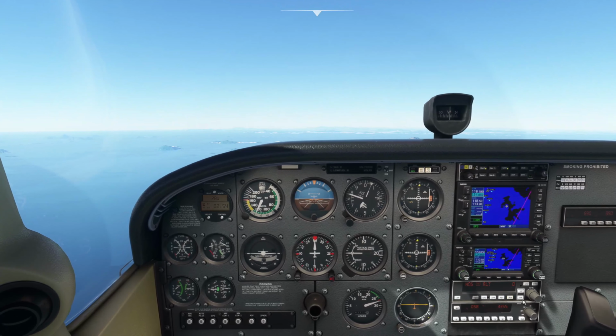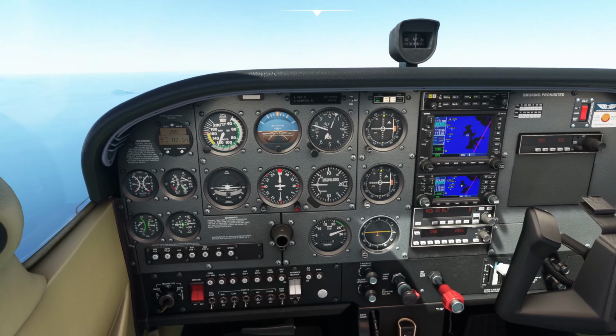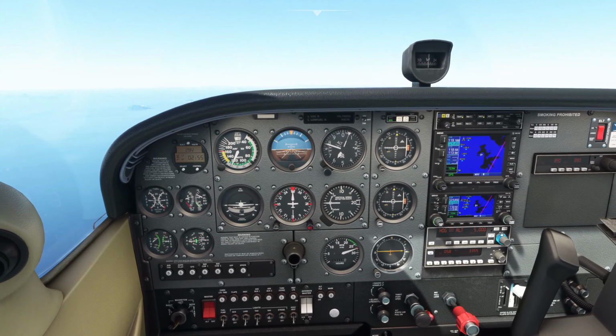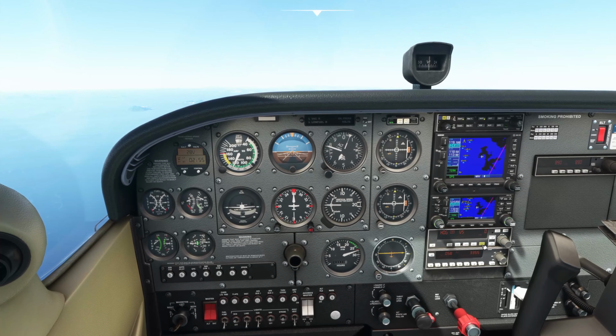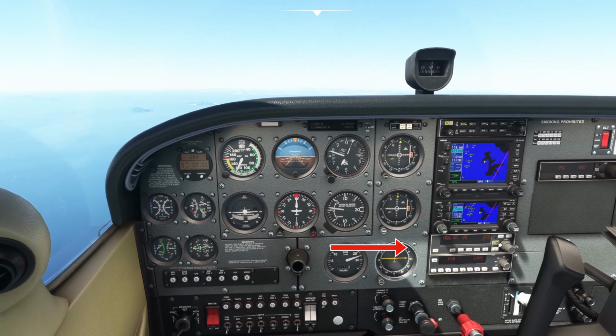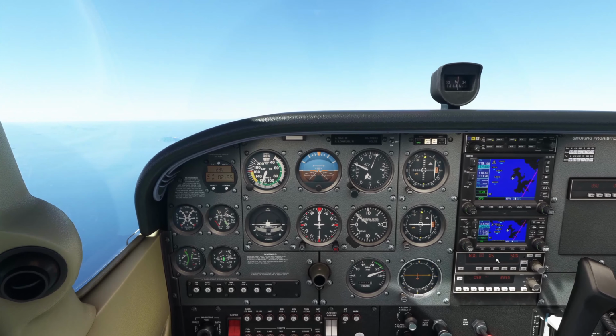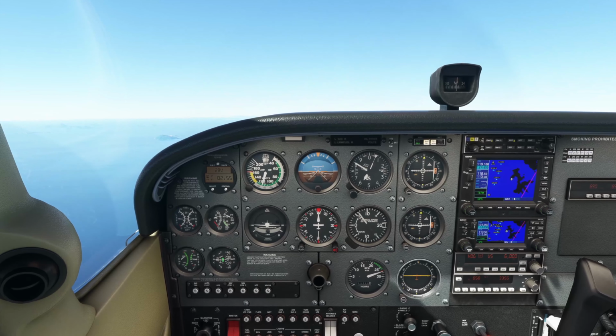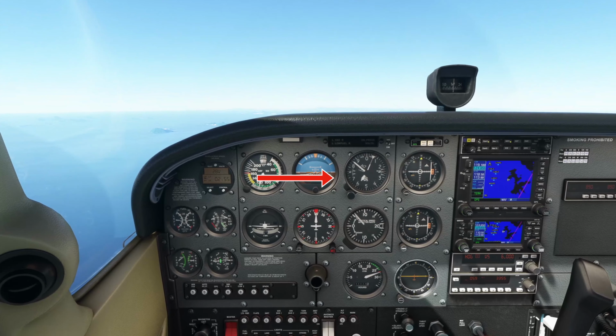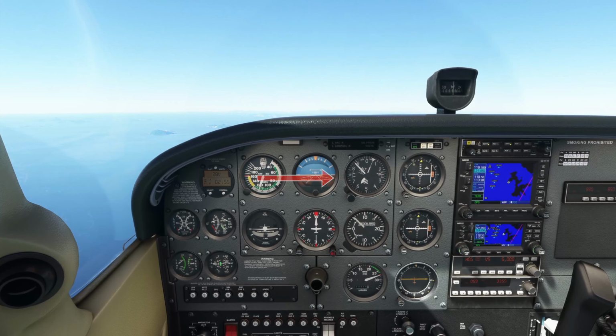We could set the aircraft up for the rest of the approach. We have lost a little height in the turn, so I use the autopilot altitude function, setting it to 6,000 and the vertical speed to achieve it. And you can see the altitude increasing.